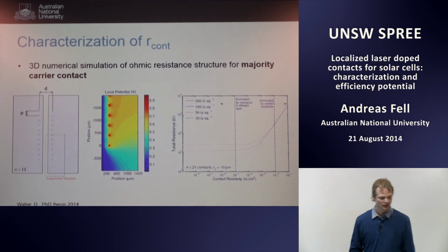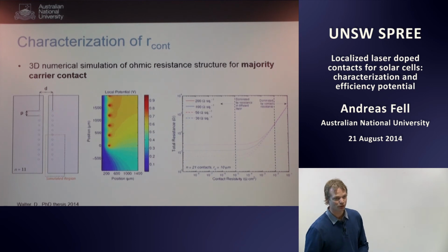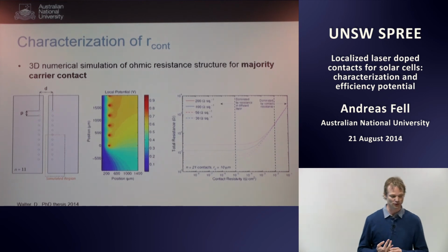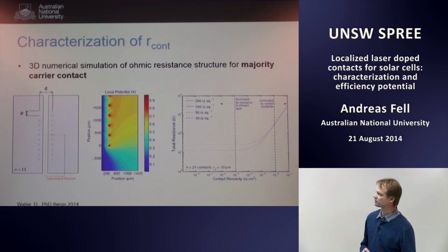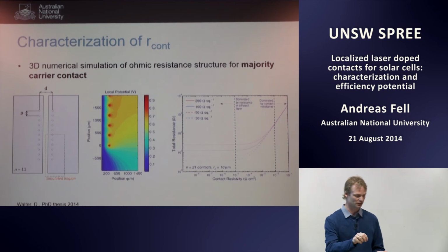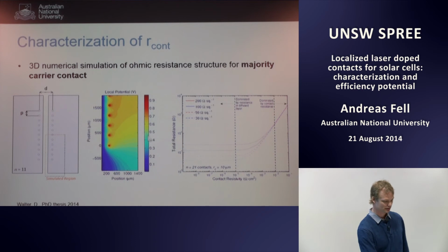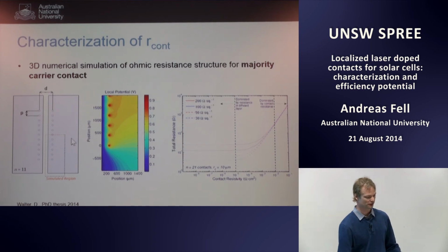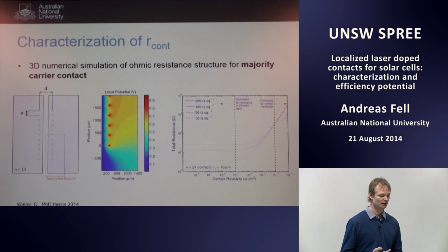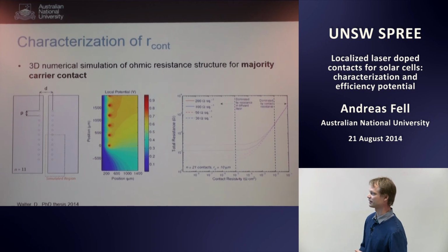All right. So now we know how to sort out the local recombination. And the second thing is the contact resistance. So we actually do a similar thing. It's a bit easier maybe in terms of simulation modeling at least. What we do is create localized contacts, make a metal pad over it, and just measure the integral resistance. And again, by 3D, now it's simple current flow simulation of only the majority carrier. So the equations are much less nasty than for a two-carrier device transport.